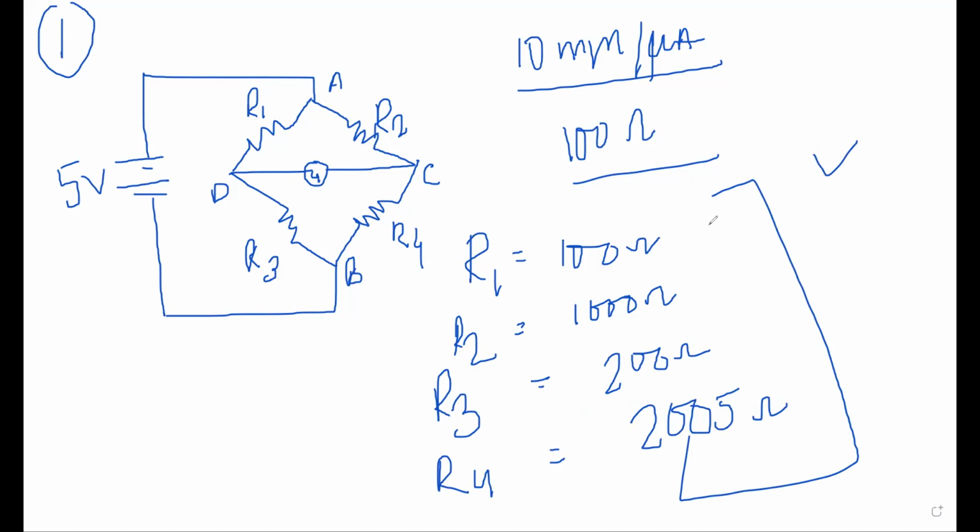So you have to find out. The bridge circuit is in a small unbalanced condition, right? Since the resistance in arm BC is 2005 ohm. I told you to calculate the deflection of the galvanometer caused by 5 ohm unbalance in arm BC, but I have already given you that the resistance in this arm BC is 2005 ohm. So do the calculation first.